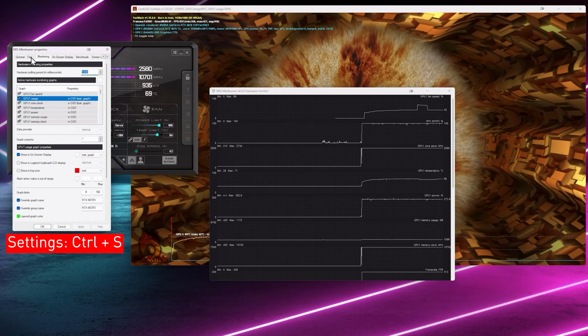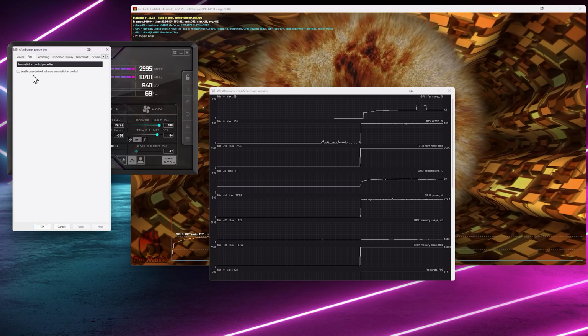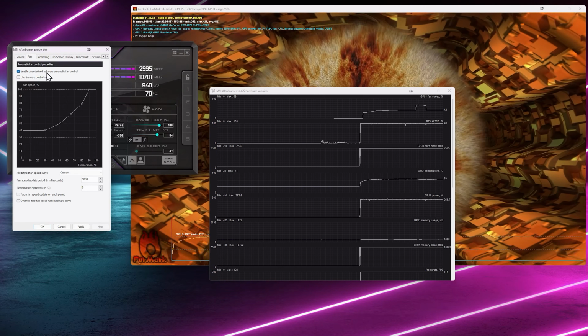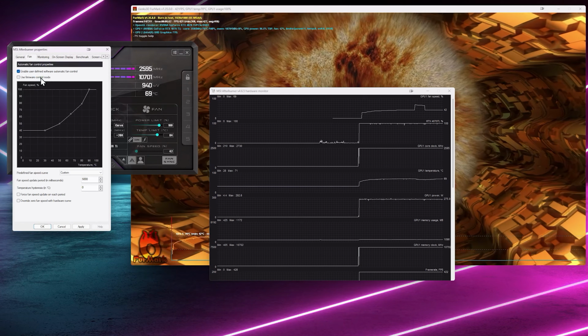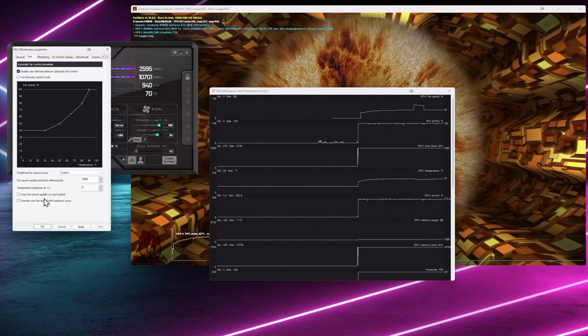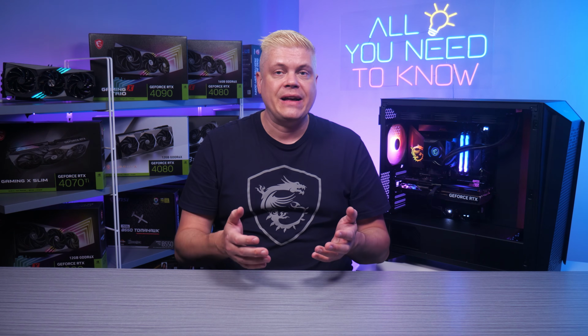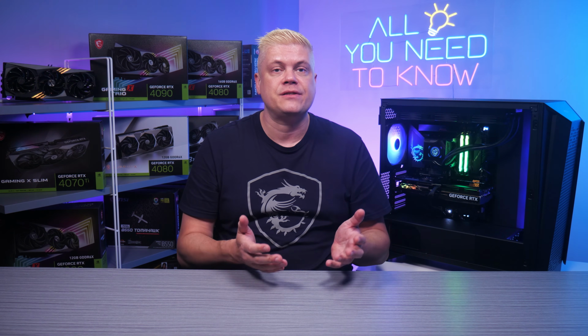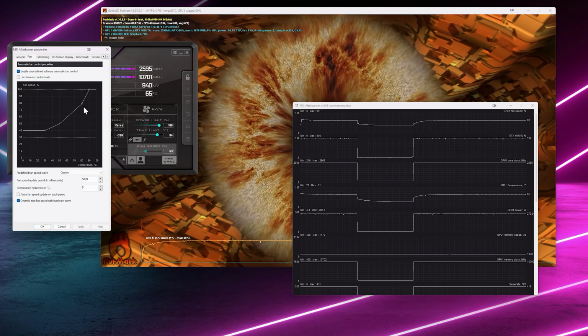In Settings, click the Fan tab at the top and click Enable User-Defined Software Automatic Fan Control. If you have a non-MSI card and don't see any changes, you can try using Firmware Control Mode. And if your fans start-stop all the time, the Override 0 fan speed with hardware curve may help. Keep in mind your case fans need to move enough air through your case to feed cool air to your graphics card. On the graph, you'll see points on a line.